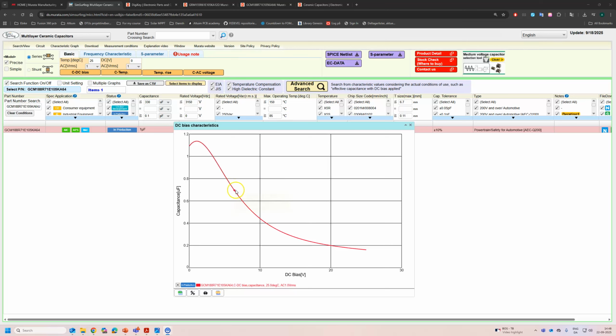So we saw this problem here on our X5R and X7R as well. Also, if you need in the future to apply more voltage, your design is not going to work even if you use X7R with 1 microfarad. And that's how we basically select the capacitor.